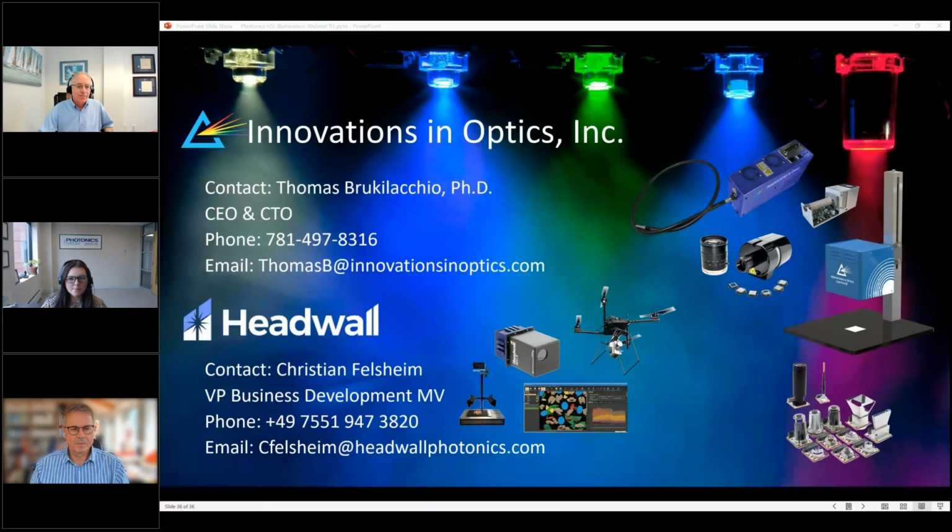Yeah, and so that's really a case-by-case basis, and it can also depend on what objects you're looking at, and whether they're wet or have specular reflection, or what the diffuse reflectivity is, what the colors are. Depending on the spectral reflectivity, some objects can be very low. If they're only reflecting 5% of the light, then you require higher illumination. So it really depends on what you're looking at, how fast you need to go. But in general, the better the uniformity, the better line speed you're going to have.